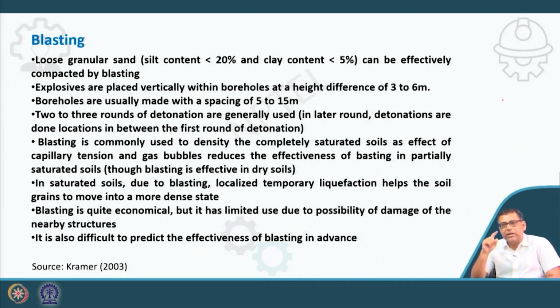And one more thing: in dynamic compaction, we can design in advance. This is the influence zone I want to compact, so what would be my weight? What would be my height of fall? So that we can design. But here with blasting, it is very difficult to predict the effectiveness in advance.